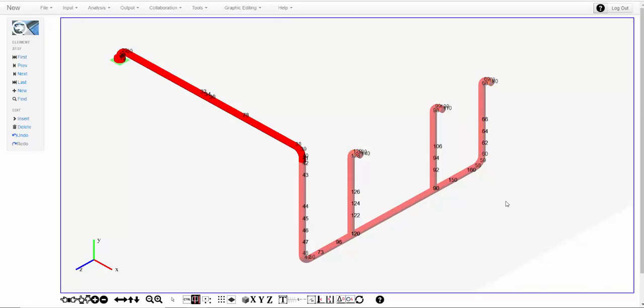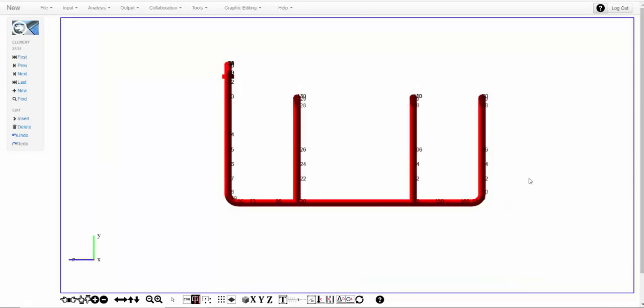So now if I look at this in X view, I see that these things have all lined up, and we have a 4-inch pipe running from here to here. Now I can build these, draw these in. I can go to this draw mode. This is D, where I click this draw mode icon here. I say I want to draw from here. It builds a little circle around this node down to this one, page down, and it registers. I go here, click here, I get the little circle showing I'm drawing from that node down to this one, page down. Okay, that looks good.